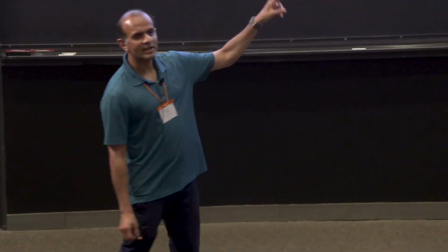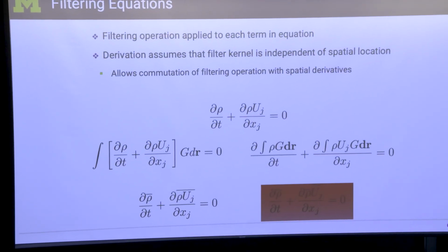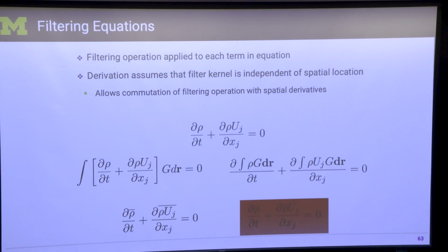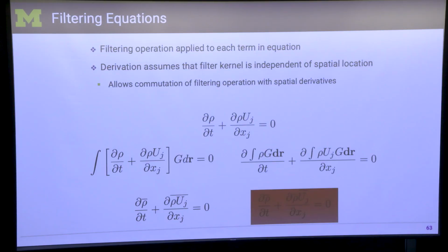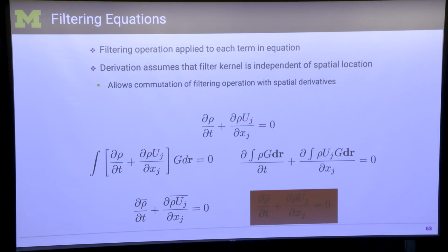So I have made special assumptions on G to get rid of it. But by getting rid of it, I have an LES equation that, for all practical purposes, has no true meaning. It's just another equation that looks like the original equation. And if you didn't know anything about CFD and I gave you that equation, you would solve it using some coarse mesh anyways, because you're not going to solve using the finest mesh. And if you did that, you're already doing LES because you're not using the finest mesh, and you're solving the same equations. So this is very important.